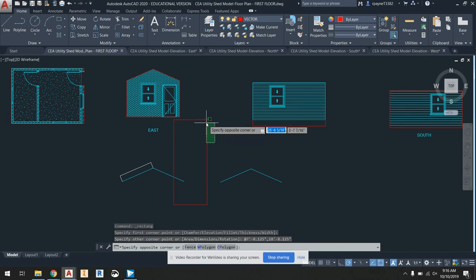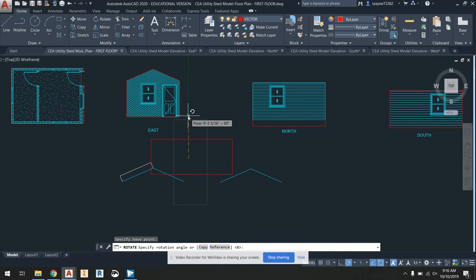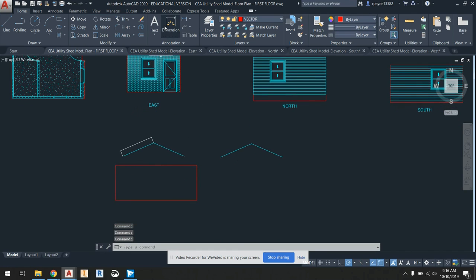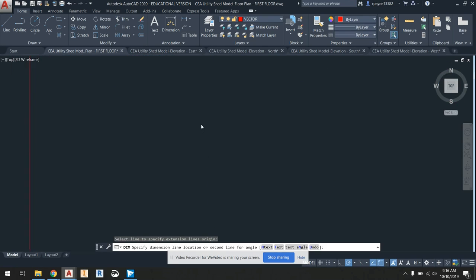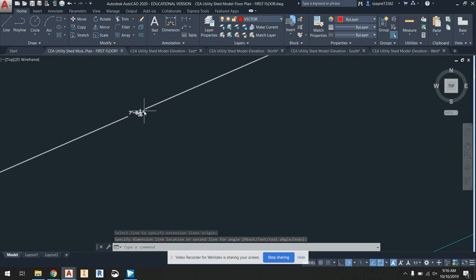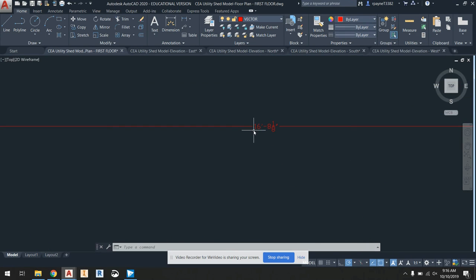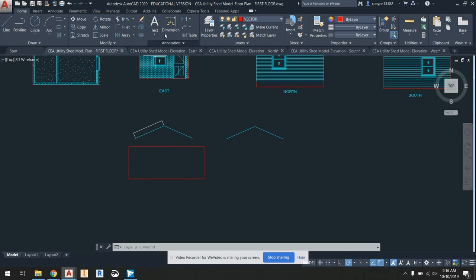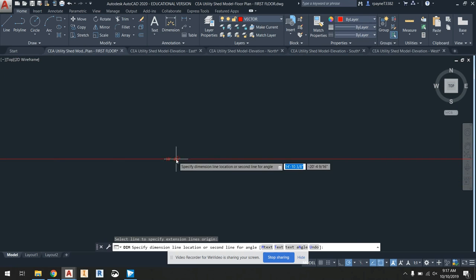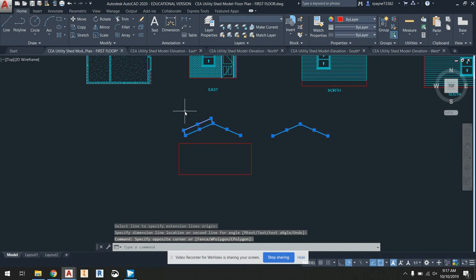All right, I made it vertically instead of horizontal. I can just do a quick rotate here to get the orientation I want. So rotate it 90 degrees. And we can just double check our dimensions. So here, 7 foot 8 and 1/8, and 7 foot 8 and 1/16. It's an extra 1/8 of an inch long. Okay, that's not that big of a deal. 16 8 and 1/8. I want it 1 foot extra on either side. 18 8 and 1/8. Good, excellent. So there's one roof panel. I need to double this up, so I can get rid of these now.